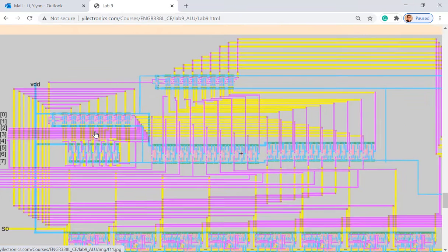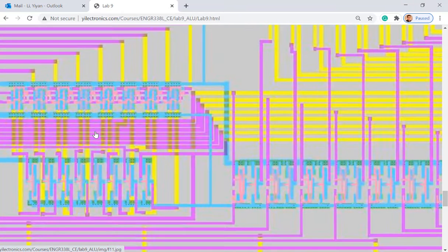Just for example here, when you are looking at this multiplexer, I have all different levels of subcells in only this part, not to mention the entire thing. In this little multiplexer, I have a multiplexer as the highest hierarchy, and I have a little inverter as a very bottom level subcell. I did a lot of LVS and DRC checks with this little inverter.